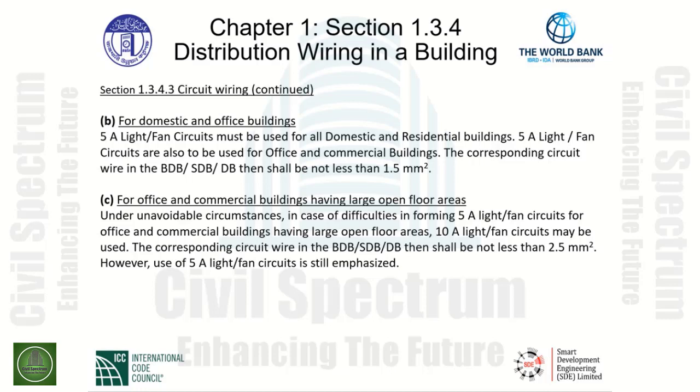This particular section sets forth the maximum ampere rating of a light fan circuit, as well as giving the minimum wire size of 1.5 square millimeters for these circuits that serve lights and fans in domestic and residential buildings.